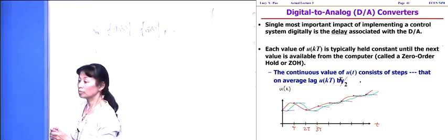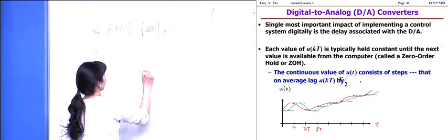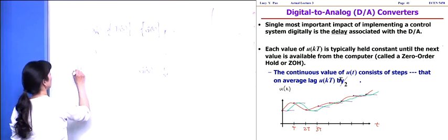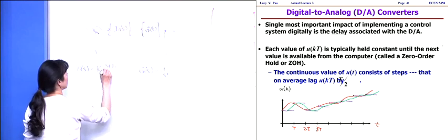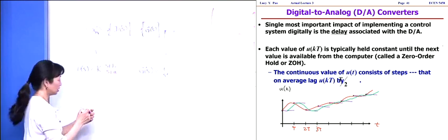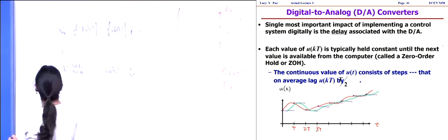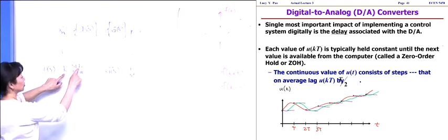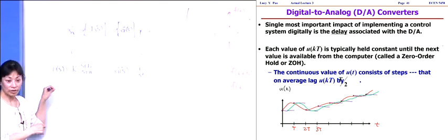Okay, so in part A, you're just designing that lead compensator, which is of the general form, let's say, some gain K times s plus b over s plus a, right? And you design a D of s, so you're choosing particular b, a, and K, so that the closed loop poles are at some specified locations, or the dominant poles are at some specified locations.